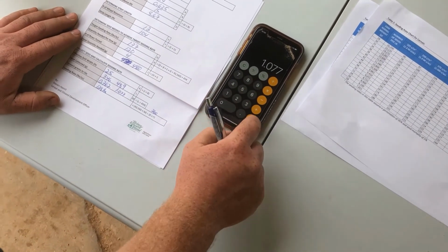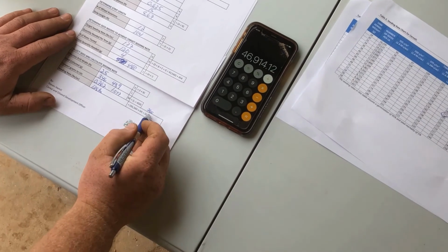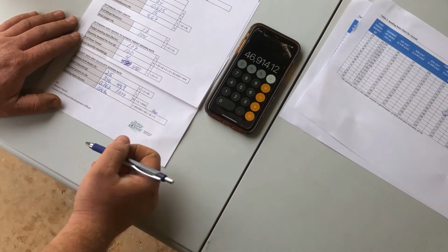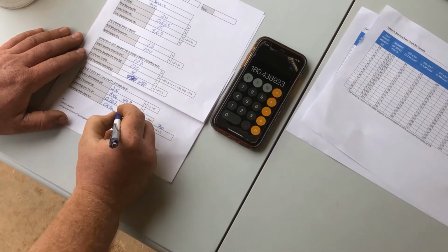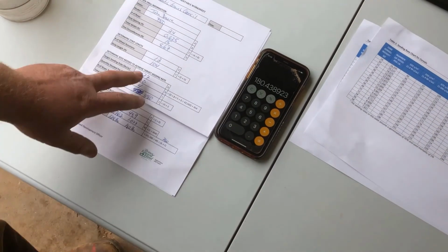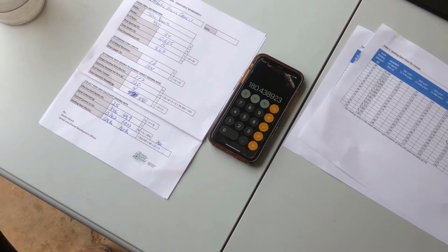And then we're going to divide that by the 260, which we determined earlier, which is the effective drill width by the strip length. So that gives us a seeding rate of 180 pounds per acre. We were targeting 177, so we're within our 2 to 3%, so I think we'd be happy with that. As we were looking for, we can head to the field and we can seed with confidence.